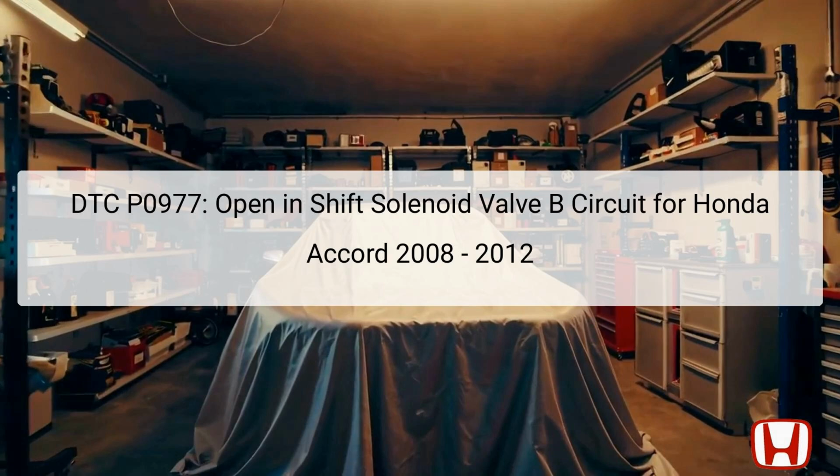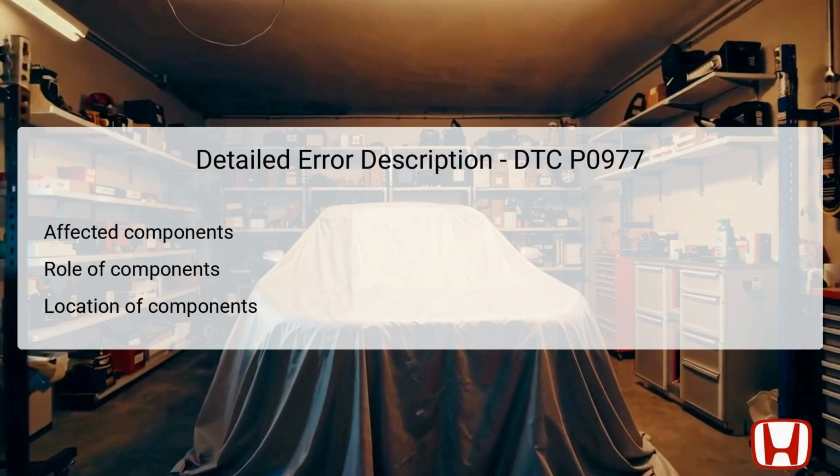The Shift Solenoid Valve B is typically located inside the transmission assembly, connected to the powertrain control module, PCM, via electrical wiring. It is important to note that this DTC is caused by an electrical circuit problem, rather than a mechanical issue within the transmission itself. The error DTC P0977 indicates an open circuit issue specifically related to Shift Solenoid Valve B.